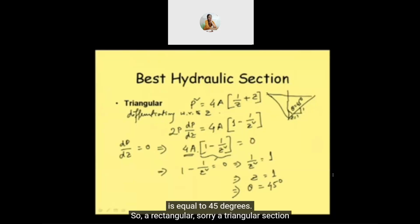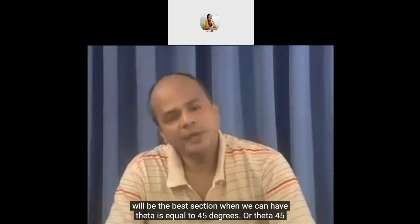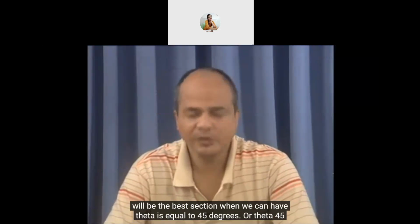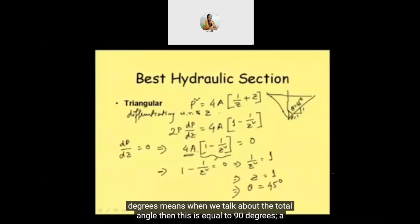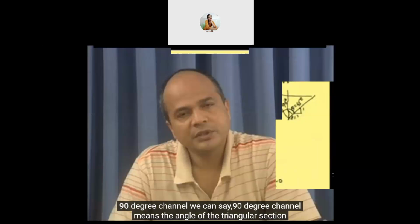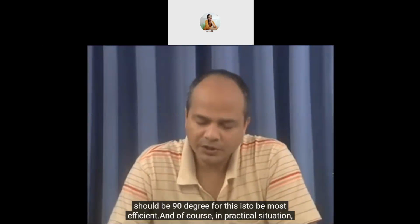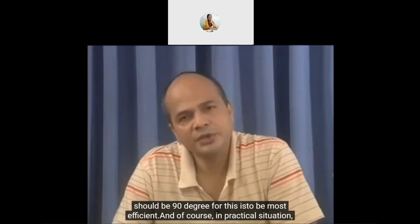So a triangular section will be the best section when theta is equal to 45 degrees. Theta 45 degrees means when we talk about the total angle, this is equal to 90 degrees. So a 90 degree channel means the angle of the triangular section should be 90 degrees for this to be most efficient.